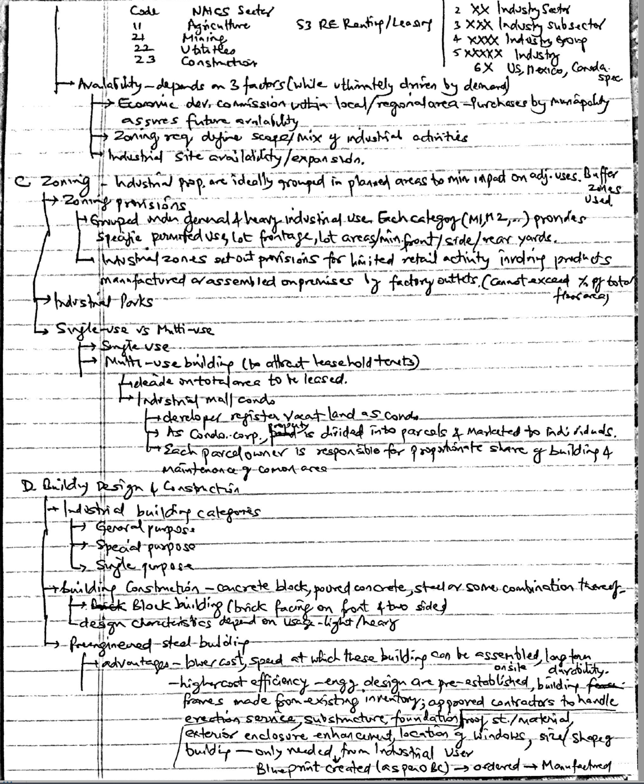Design characteristics vary depending on whether the intended use is light or heavy industrial. Heavy industrial requires additional structural floor columns and ceiling reinforcement, along with higher bays and clear height to address such things as stationary or moving cranes, stamping equipment, large processing equipment, and raw material storage.